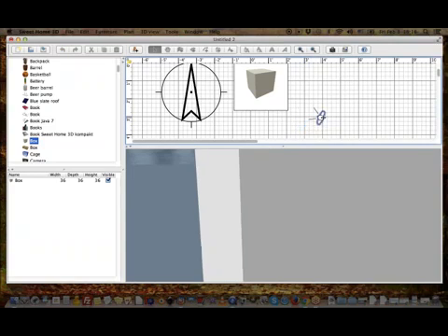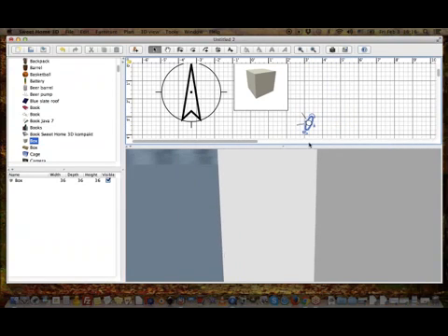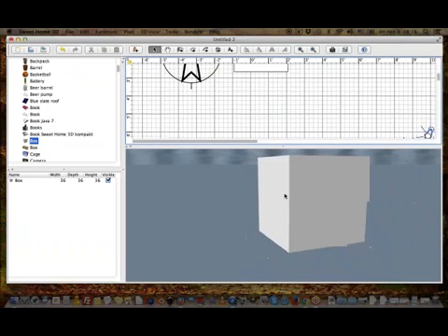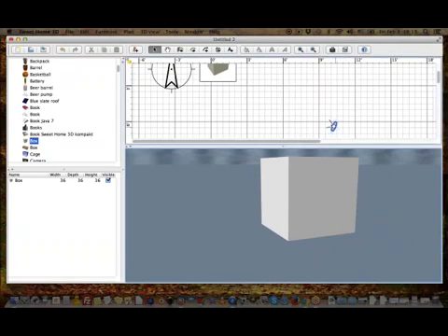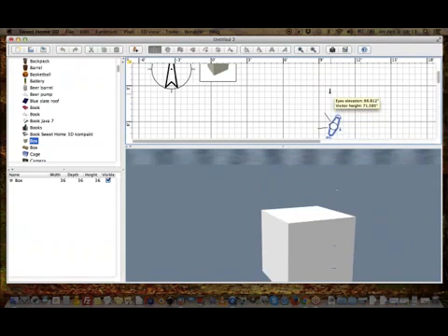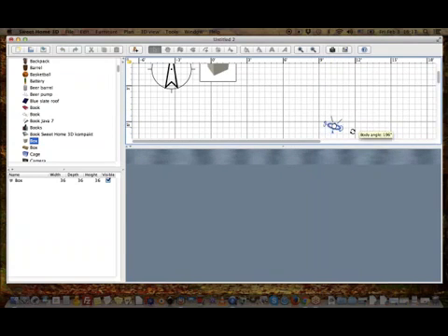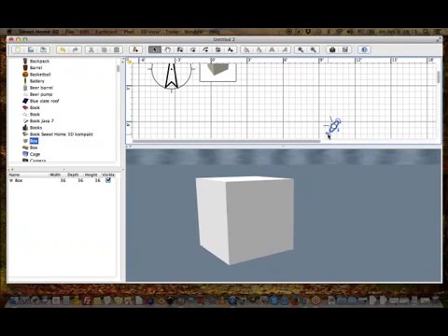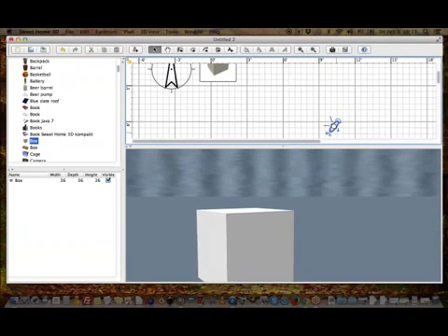So basically the character has 4 points of manipulation, can move it around in space. And you can also do that on this box right here. You can change the eye level, like right here, up or down. You can change the orientation of the body angle, or you can change the head angle. Means a person, is it looking up or down, right? So this can become really useful once you've designed a house if you want to check details on the interior that the bird's eye view does not allow you to.